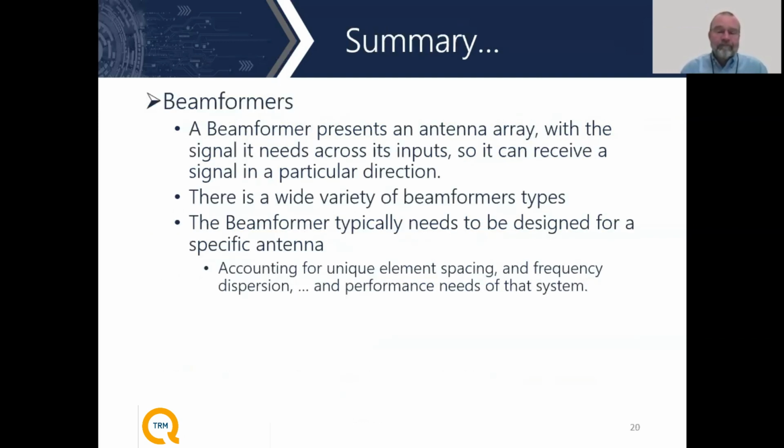Sure. The top summary here really is that beamformers act as the interface between the antenna itself going back to the rest of the avionics. Because of that, there's a wide variety of beamformer types. We like to talk about the Butler matrix, that's kind of a favorite one for us, as well as the monopulse comparator and a few others. But realize that there are lots of other beamformers that don't have formal names. And these are all things that we certainly like to speak to the customer about, to find out really what their needs are.